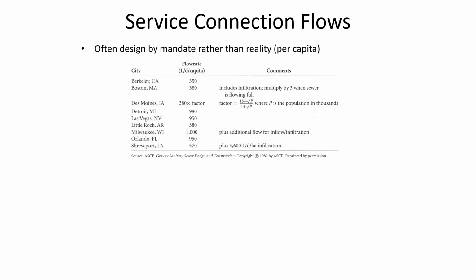But in a city, just using New York City as an example, you've probably heard the saying that New York's the city that never sleeps. There's people who are always awake. So a big city tends to have not only geographic reasons why the wastewater has fewer peaks, but also population-wise, it's going to be less peaking the bigger the city is. And so that also accounts for how much water is going to be used.